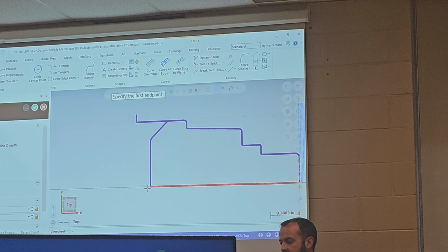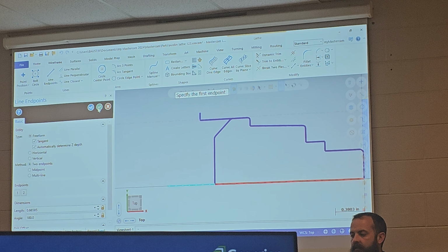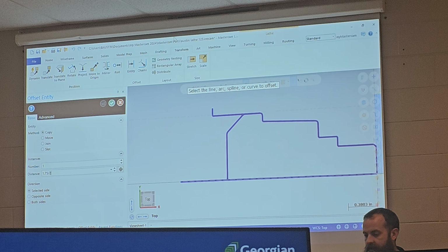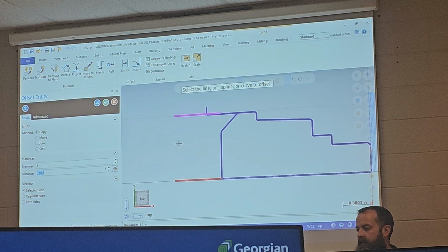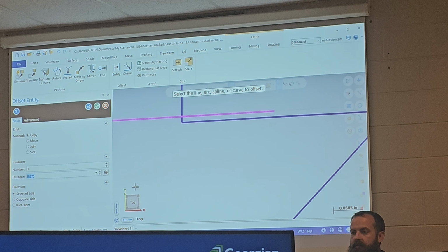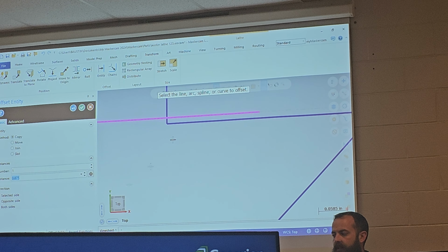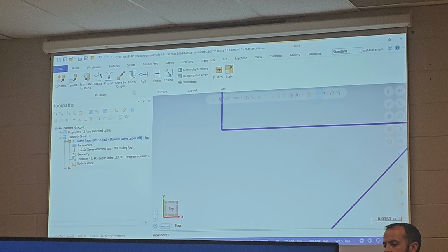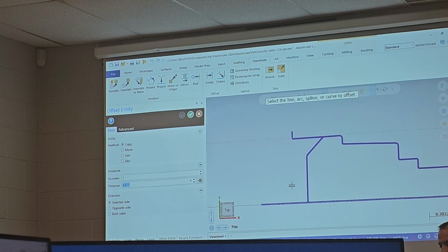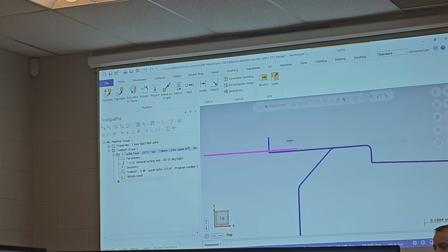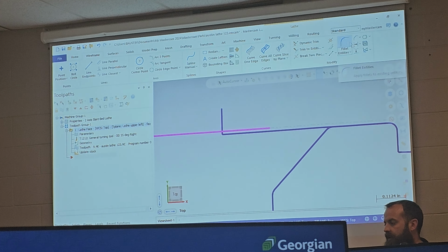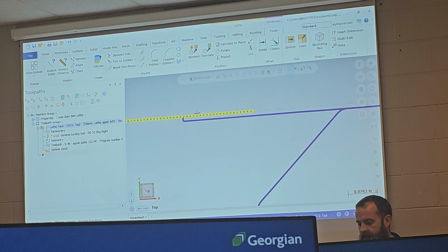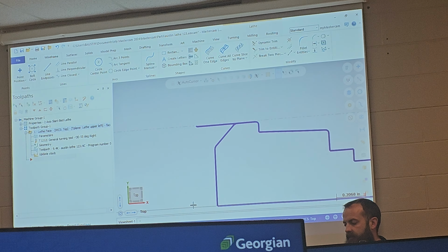I'm going to draw a line here to represent the middle. And I go transform, offset, 1.75 divided by 2. So the radius of the bar. Okay, and I get this. Okay, the reason I'm doing that is I'm going to trim, offset this, that way. I'm going to go wireframe and trim this part. Okay, I can delete this, and I can delete that.